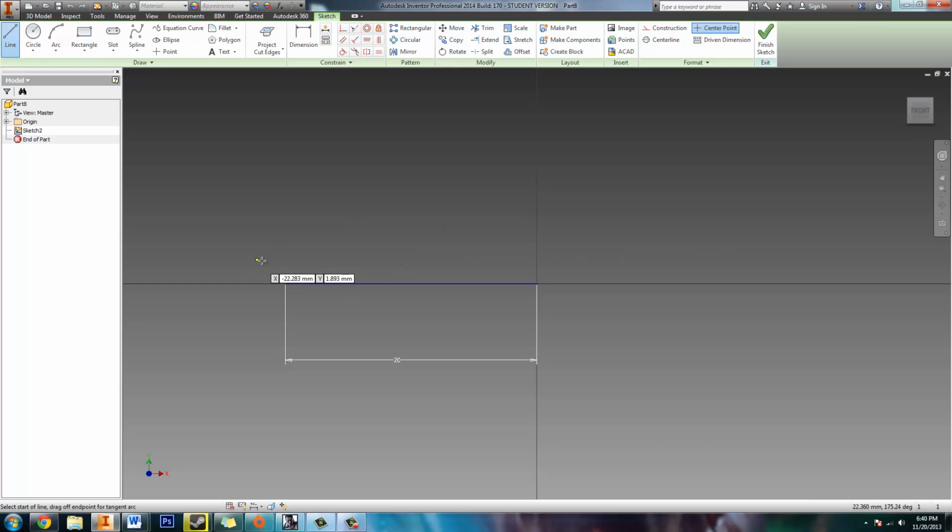I'm going to continue using the line tool to make the side of the racing track. To switch between different dimensions, whether it be degree or the length of the line, you can use Tab to switch between them. So I'm going to make this 135 degrees, and I'm going to make this 6 millimeters. I'm going to make this line exactly the same, and make it 1 millimeter in thickness. This is also going to be the same. I'm just going to finish that there.